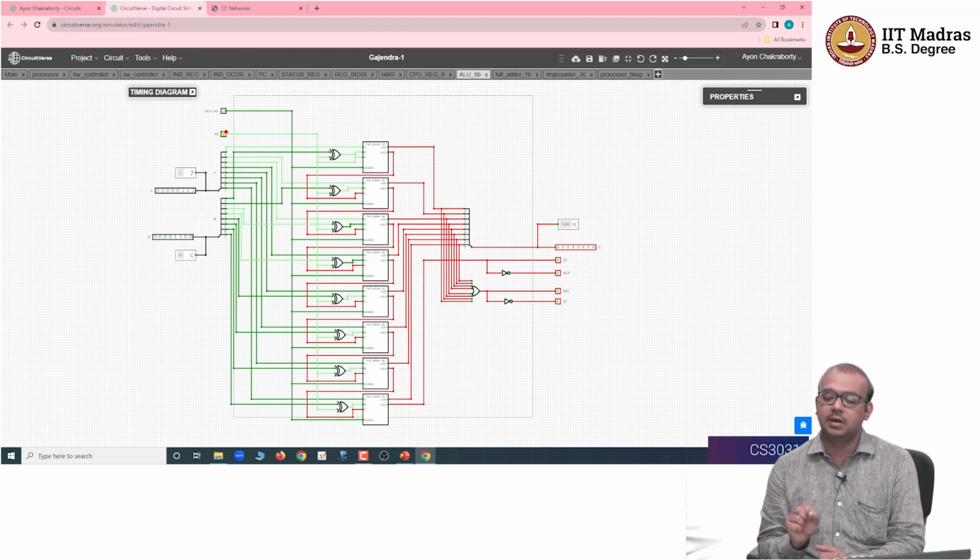If it is 1, 0, the decoder's third output goes to an AND circuit, which basically takes again A and B, finds the AND of them, and instead of a sum, you have an AND output. Similarly, if it is 1, 1, instead of taking A and B, it is just going to take A and find the complement of A, and the output is NOT of A.